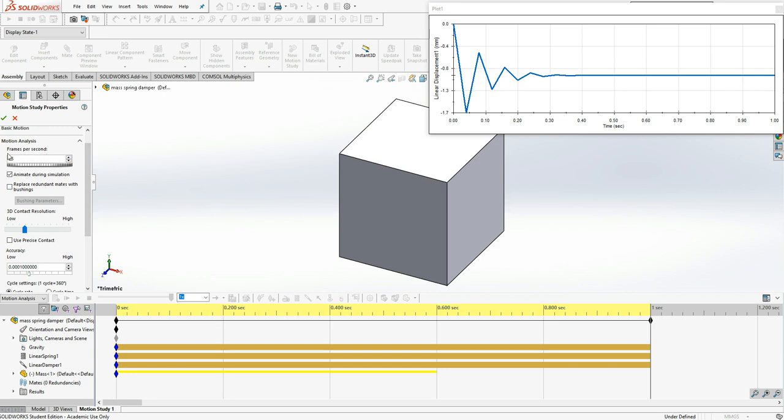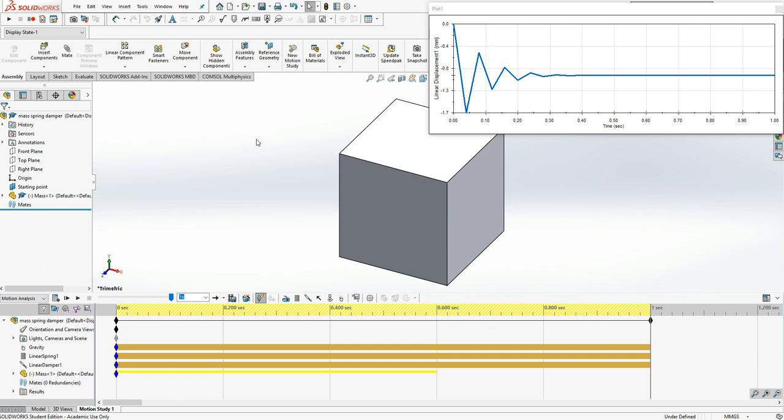This is very interesting. This is frames per second. With frames per second, what it tries to do is slow down the process of calculation. It tries to stay with this time step, but it doesn't edit the time step. It gives more time for computational processing. So what we're going to do first is multiply that by 10. So we've got 250 frames per second. This might not heal it, but let's just try it.